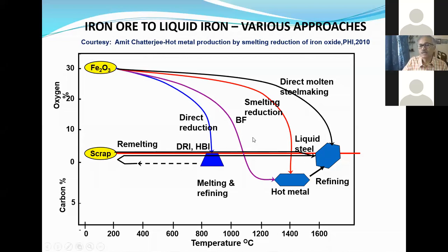So that's why the electric arc furnace today is evolving, because the advantage of the electric arc furnace is that you can take the charge in any proportion. Cold charge and hot charge, in any proportion you can use. But the basic oxygen furnace, or the LD furnace, has a limitation on the cold charge, because it is an autogenous process. Heat is generated by chemical reaction. So it has a limitation on taking the cold charge. Some excess heat is generated from impurity oxidation. Impurity oxidation sustains the BOF process, as well as some excess heat is generated, and that you can use to melt some amount of the cold charge, but there is a limitation, around 20% you can use.